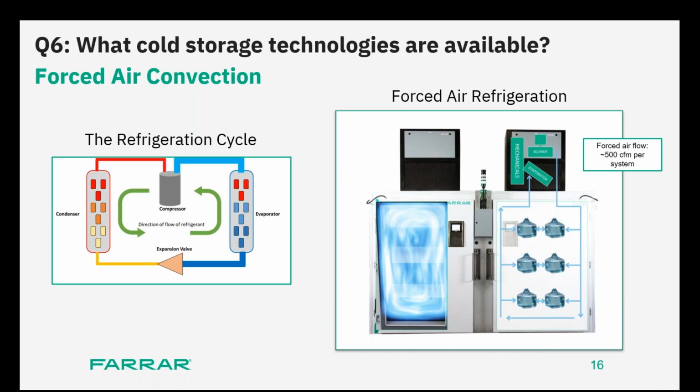And finally, we have this really innovative auto defrost function that's built into the evaporator. This aspect is tied to the first concept that I talked about, which is minimizing this frost issue in the chamber. As I mentioned, as you're opening and closing the door, you're going to have ice buildup on the evaporator. There's nothing you can do about that. In this case, the evaporator is sitting on top, and you'd still have this ice buildup.